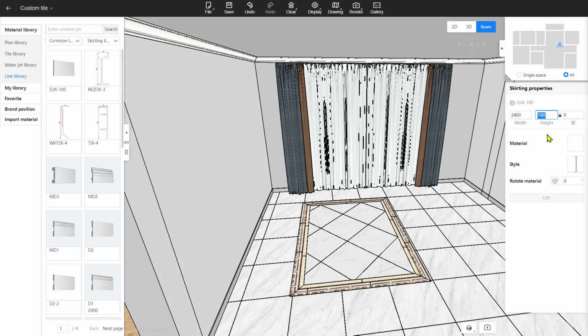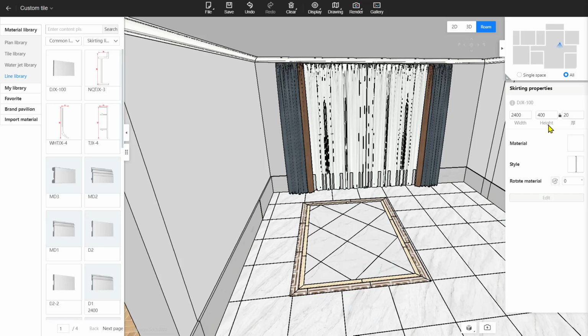The same, if you want to change it, you can change its height. Like change it to 200 and hit enter key to make them more obvious. And here is its thickness. You can change its thickness here, like change to 20. Hit the enter key. And you will see the height will also change, which means the height and the thickness are locked together. If you don't want them to change together, you can hit this little lock. Then now it is unlocked. So when you change it to 10 like this, then the height will not change. Change it back to 200.